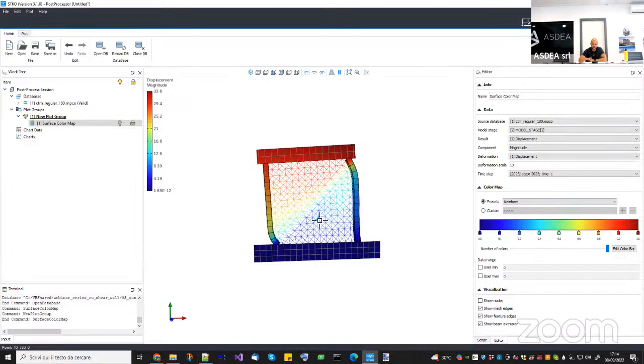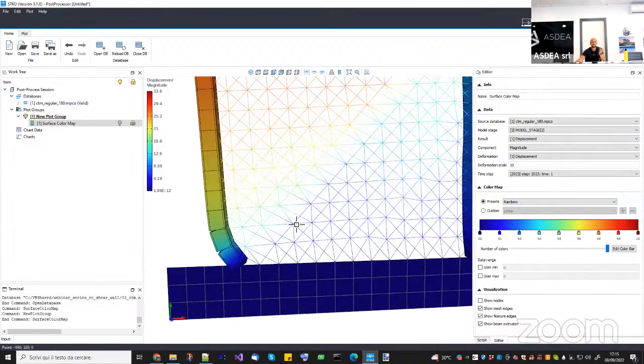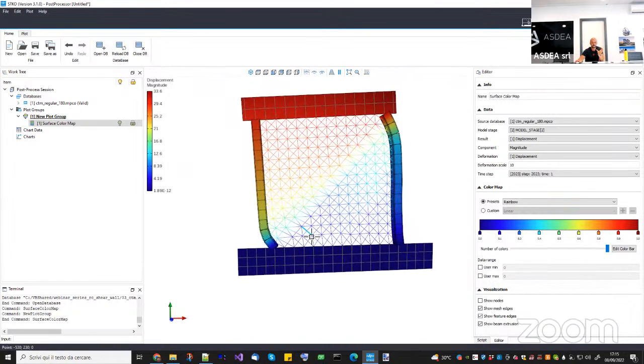Now, fracture energy regularization is a way to make sure that the total dissipated energy is the same. But actually, fracture energy regularization was a very rough method that works perfectly for a constant state of stress. But when you have bending and shear, this is not perfect anymore because you have something called size effects. So in this case, for example, the microstructure has a physical size, which is actually the spacing between the rebars.